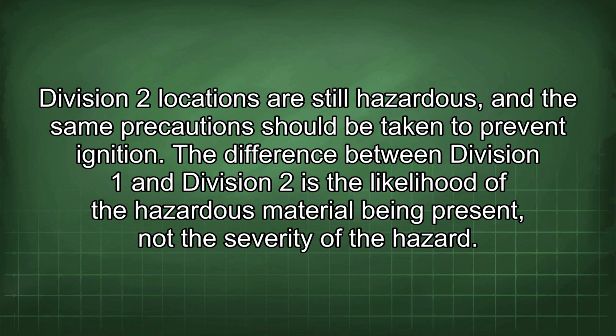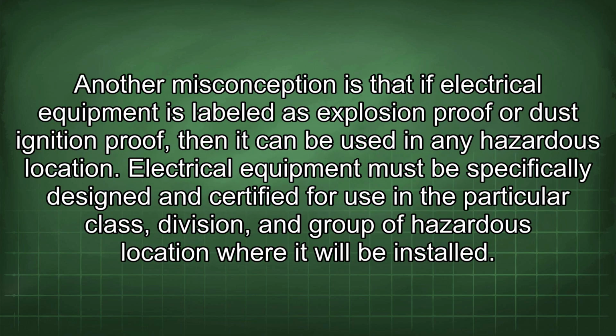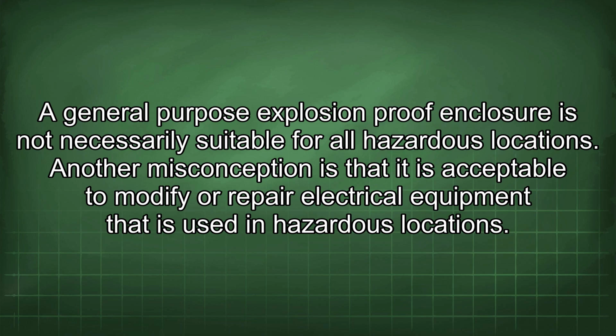Another misconception is that if electrical equipment is labeled as explosion-proof or dust ignition-proof, then it can be used in any hazardous location. Electrical equipment must be specifically designed and certified for use in a particular class, division, and group of hazardous location where it will be installed. A general-purpose explosion-proof enclosure is not necessarily suitable for all hazardous locations.